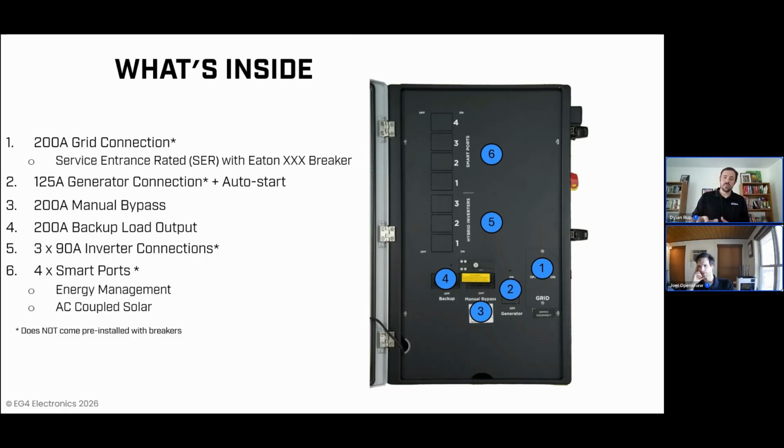Now, I'll also go ahead, Joel. Yeah, if you're installing onto a system that already has a 200 amp disconnect, you're not going to be required. Dylan was correct. It is the CR2 Eaton breakers you're looking for there that are going to be compatible with our GridBOSS, as well as, I guess, we'll jump into the other ports there, but we'll also be compatible with Eaton breakers.